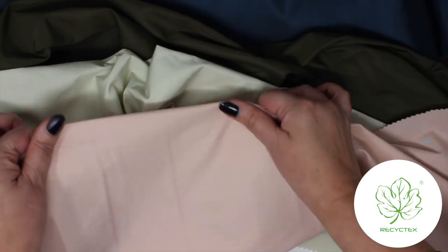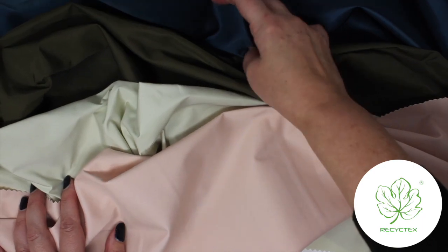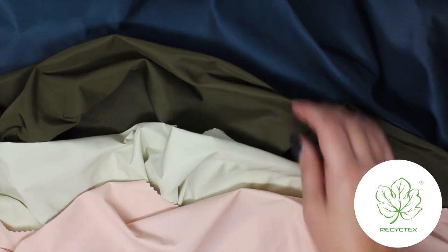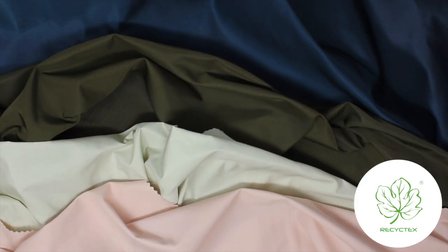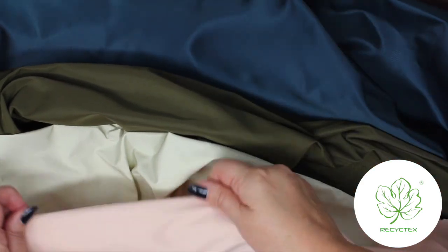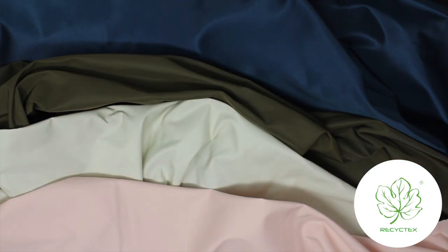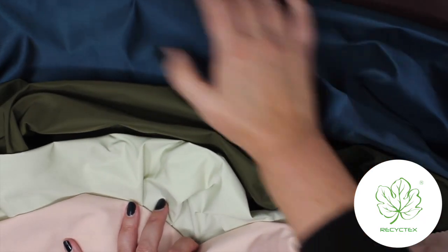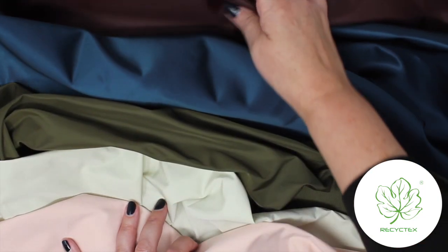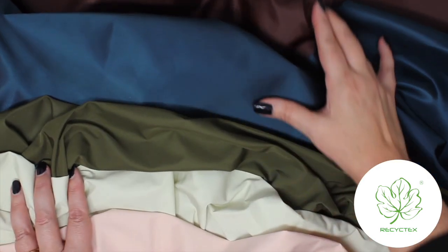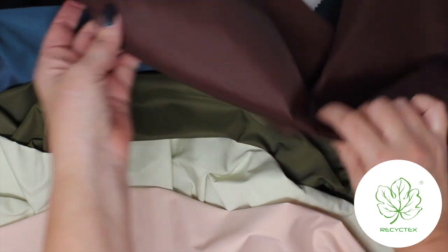synthetics. One of that is mechanical recycling, and that means that we take a material, either a used textile or from a PET plastic bottle, and we're mechanically breaking that down by either shredding, pulling apart, and then it's melted down and formed into pellets. And those PET pellets then move on to the manufacturing stage. So they are remelted and extruded out into new fibres. So that's the more obvious type of recycling that you'll come across.